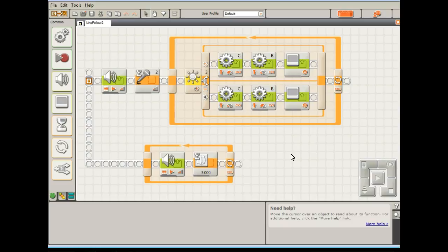So I'll go up here. Adjust the sensor to see white light or white. Right, that's what you'll do. You'll use that, and we'll show you all how you do that. You calibrate the sensor. So you'll go over there and put it on the white line, and then you'll see what that sensor puts out. Then you'll put it on the gray, and see what that sensor puts out, and that's where you'll set your limits in the middle. So that's where we'll use that view option.